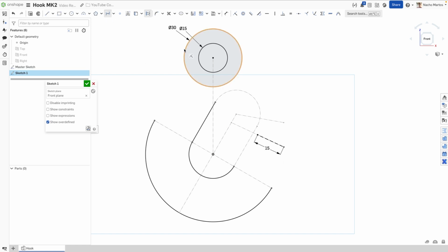So now we want to select the Bezier, and most of these are going to be 2-degree Beziers. They do not need to be construction geometry. We're going to just make these Beziers 2 degrees between some of the circles that we've defined and the rest of the geometry. Make sure that you do not have row constraints as you make those Beziers, or you'll have to deal with those row constraints later. Again, 2-degree Beziers. Now, there's one 3-degree Bezier here, which is just the very tip of our geometry. And now we can see that that's being closed.